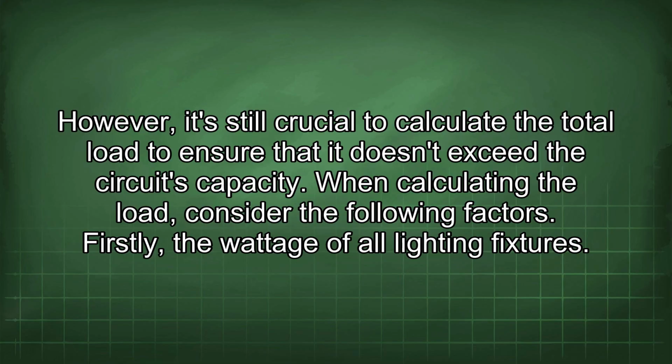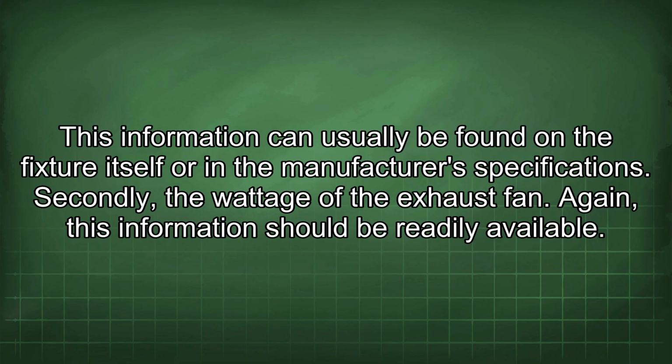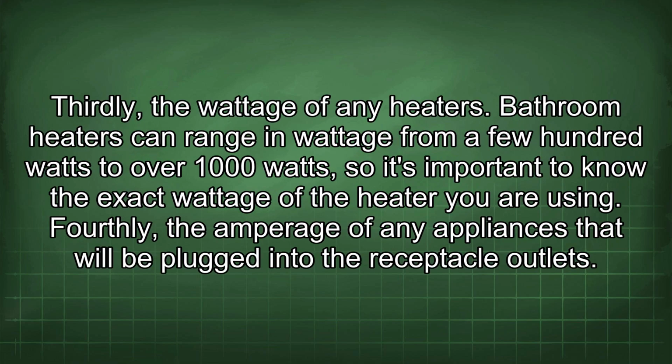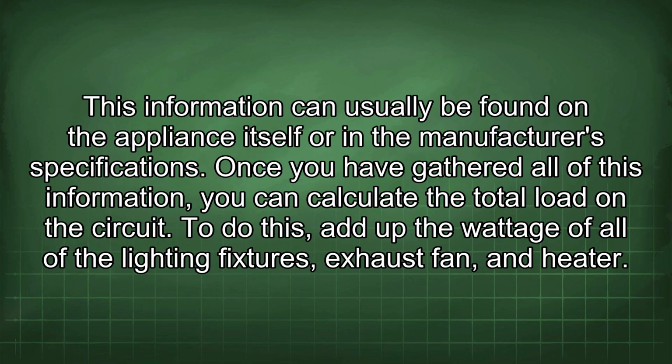When calculating the load, consider the following factors. Firstly, the wattage of all lighting fixtures. This information can usually be found on the fixture itself or in the manufacturer's specifications. Secondly, the wattage of the exhaust fan. Again, this information should be readily available. Thirdly, the wattage of any heaters. Bathroom heaters can range in wattage from a few hundred watts to over 1000 watts, so it's important to know the exact wattage of the heater you are using. Fourthly, the amperage of any appliances that will be plugged into the receptacle outlets. This information can usually be found on the appliance itself or in the manufacturer's specifications.